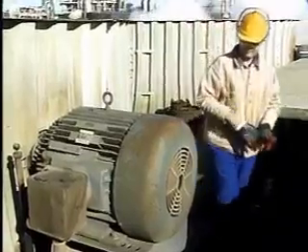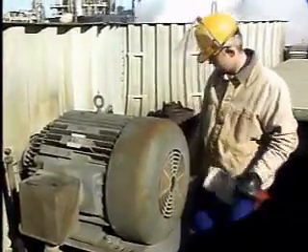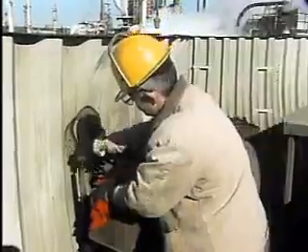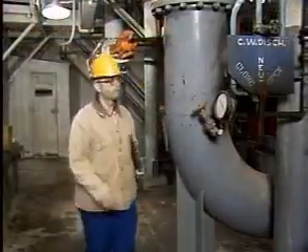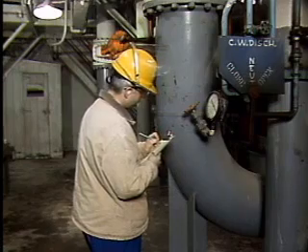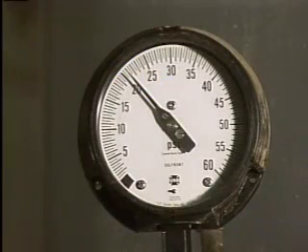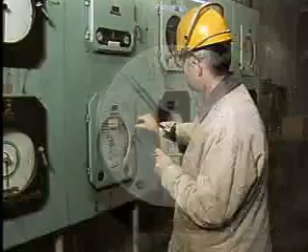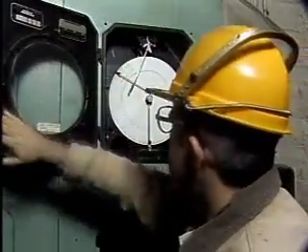The fan, along with its gearbox and driver, should also be checked for unusual noises, excessive vibration, and overheating. Also, the lubrication of the fan and driver should be checked. In addition to the checks we've just covered, it's also important for operators to regularly monitor cooling water temperatures and pressures to make sure they're within normal ranges. For example, the discharge pressure of the circulating pump should be checked to ensure proper flow through the system. Also, water temperatures should be checked to see if the correct amount of cooling is taking place.